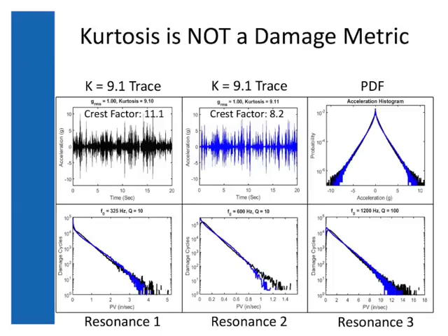I think I'm just going to leave this on: unless you are required by specification to use kurtosis, you are always better off setting a Gaussian level that does the damage you want.